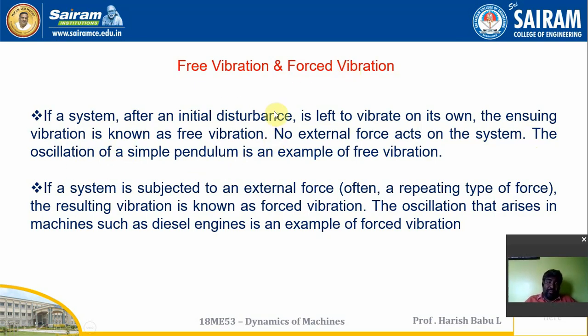If a system is subjected to an external force, often a repeating type of force, the resulting vibration is known as forced vibration. The oscillation that arises in machines such as diesel engines is an example. There will be a continuous run of the pistons, which creates a vibration in the engine. So that engine will be continuously vibrating only because of the external force. If that external force stops, the vibration automatically reduces for the system.